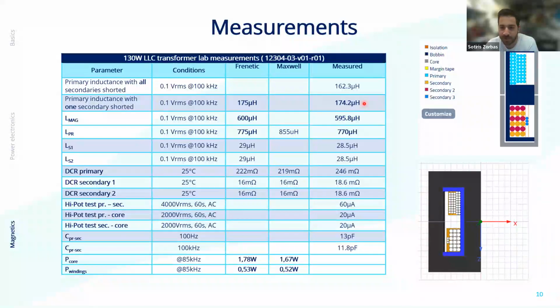So this was one key point that I forgot to mention, because the usual route to getting the leakage right is trial and error. I mean, even the best approaches cannot get it exactly right at first go. Here we got it, because what you can see here is a 5 millimeter gap between the windings.